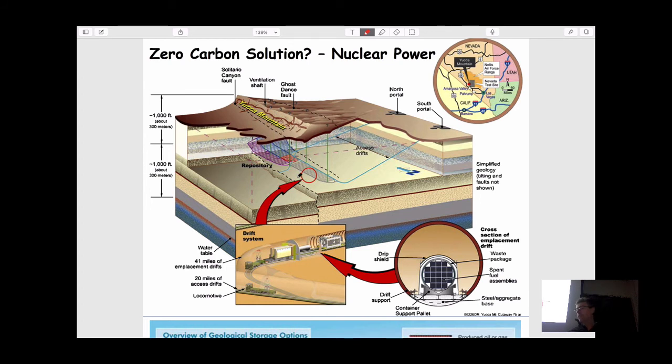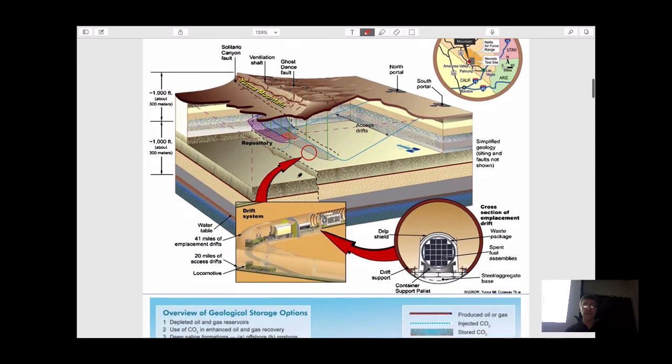The preferred method being investigated now is to drill very deep boreholes, maybe 5 kilometers deep, probably half a meter in diameter. You have these circular canisters that contain the waste, and you drop them into the subsurface, to the bottom of the hole, you put a number of them there, and then you seal it, and then you just forget about it. So that's the one. The US is the only country investigating that right now, but that seems like the preferred option.